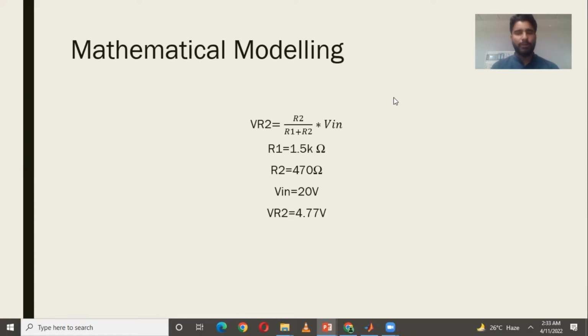Although our input value is up to 20 volts, we have used VDR circuitry to sense more than 20 volts. The voltage drop across the R2 resistor is sensed by the microcontroller and we get output from the digital pins of the microcontroller, which will send to the relay.